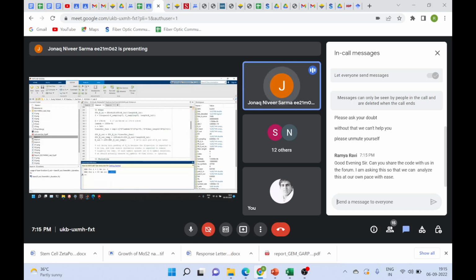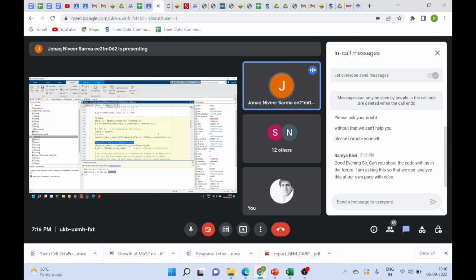The whole transformation is just this transfer function applied in the frequency domain. That is the main working function. What this whole code does is generate frames of data and send frame by frame, apply whatever impairments happen, and then try to decode it. That's it. So this is the MATLAB code that you can use to check dispersion in fiber.